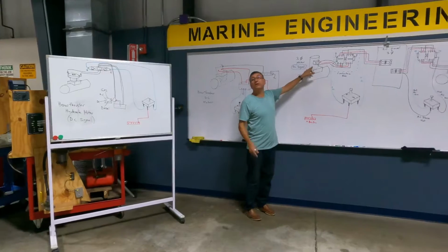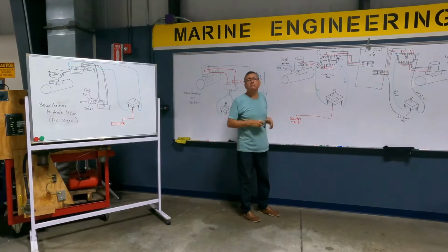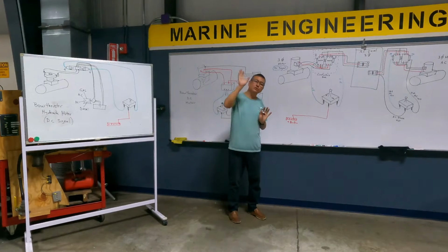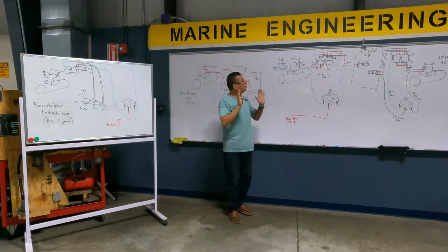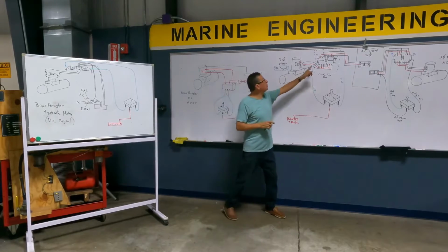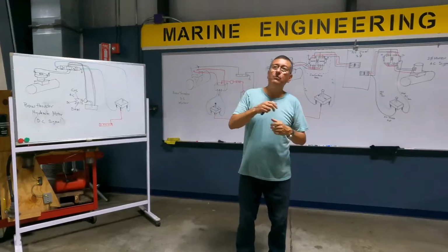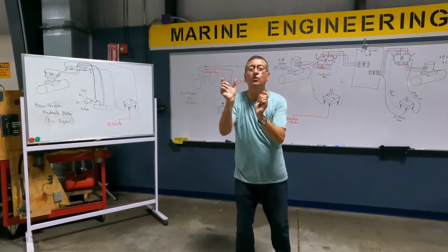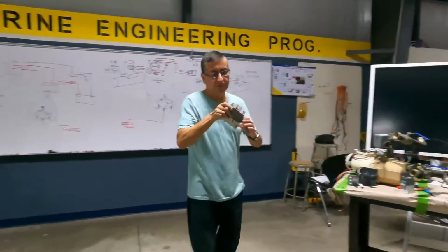The motor is a three-phase motor, and this is the configuration for that motor. High speed, low speed. I explained to you in the motors how you configure high speed, high torque, low torque. You remember the three-phase motor. And I have 2 contactors. If I have AC reversible motors, I have, pretty close to the motor, a plastic box with a couple of contactors.